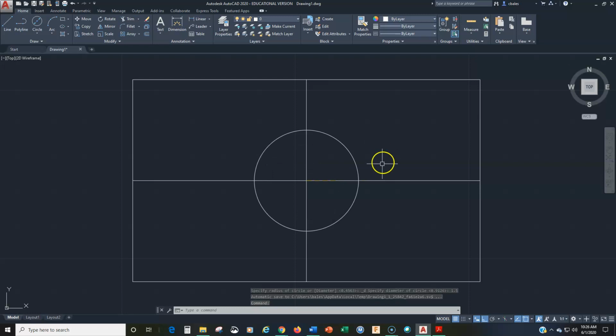Okay. Now I'm going to do a couple things here. Before I move on, just so that you can see clearly what's going on, I'm going to turn off Ortho Mode, and I'm going to go back to the polar tracking. In fact, we don't really need polar tracking on, but I just want to turn off the Ortho Mode so you can see more clearly what's going on. We'll leave Object Snaps on, okay? And let's look at the other 4 circles, okay?